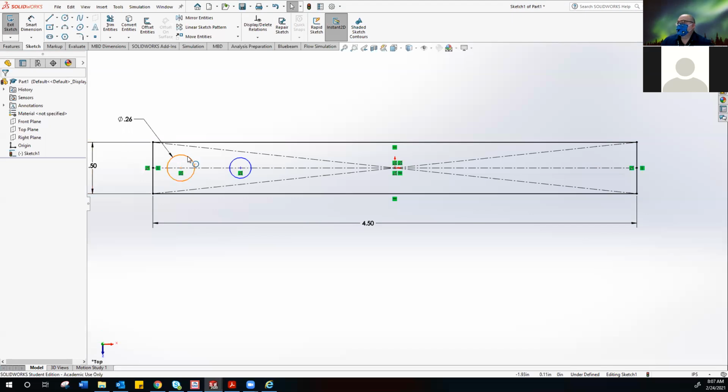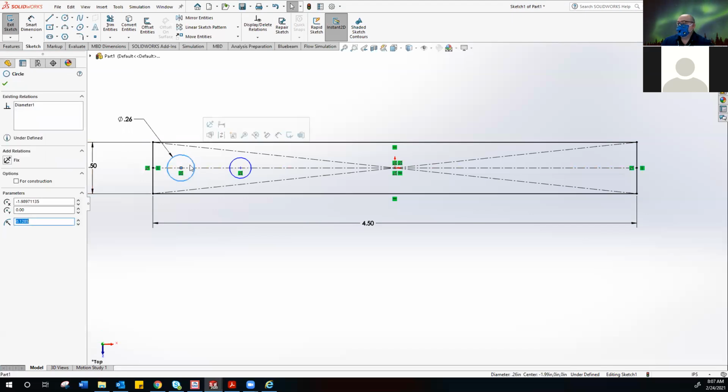Okay, so what I'm going to do is select the circle edge. You select it once. When you select that one circle, you're going to see things like you can fix the point. Don't do that. This big old anchor means you cannot move it. That locks it down. But if you hold the control key down, that's a C, T, R, L.